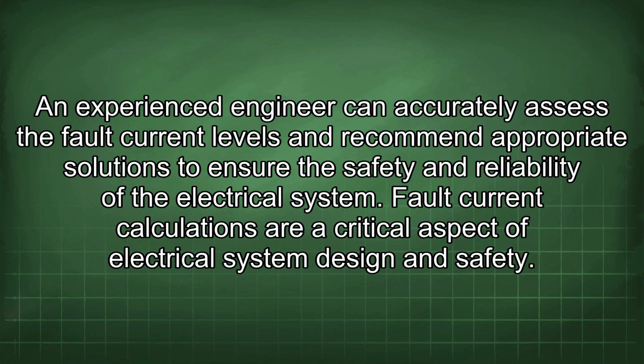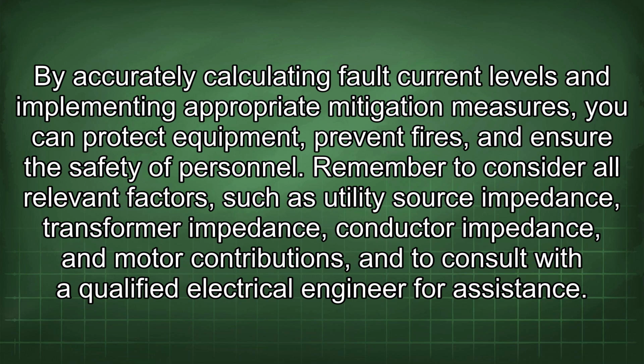Fault current calculations are a critical aspect of electrical system design and safety. By accurately calculating fault current levels and implementing appropriate mitigation measures, you can protect equipment, prevent fires, and ensure the safety of personnel. Remember to consider all relevant factors such as utility source impedance, transformer impedance, conductor impedance, and motor contributions, and to consult with a qualified electrical engineer for assistance.